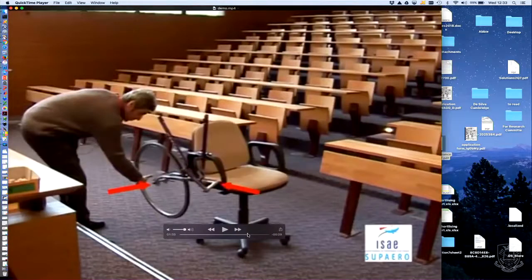So just think, what did he say? He said the spin axis, right? He didn't call them I, J, and K, but for us, this is the spin axis. It's K, isn't it? So the wheel is spinning around the K-axis, okay? And then he said the precession axis, which is the J-axis for us. And then the final one is the moment axis.